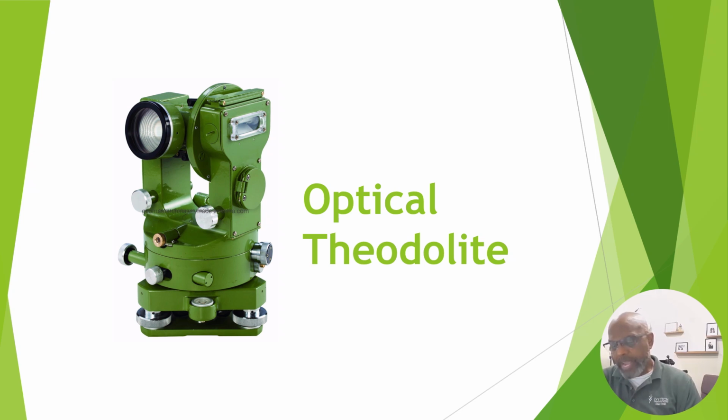The repeating theodolite contains the same upper and lower clamp systems as the transit. However, the reading of the angle is different because of the optical reading capabilities. This instrument also has a glass circle, but it does not have a scale, as it has a micrometer used to precisely read the angles. The operator turns the angle, and then uses the micrometer to align the degree index marks.